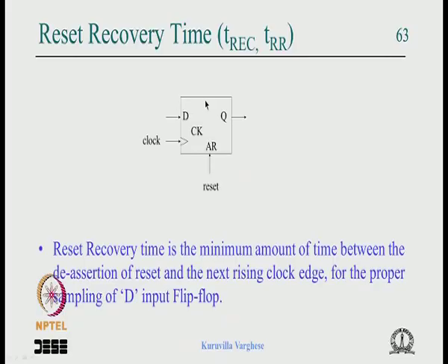Like we are not asking the right question. When you assert it, fine, the reset is driving the internal latches, you know, that's the problem. Like in an edge triggered flip flop you have a master latch and a slave latch, and this asynchronous reset is directly going to the master latch and slave latch and resetting them, and you can look at the circuit diagram for it, then you will realize why that happens, okay.